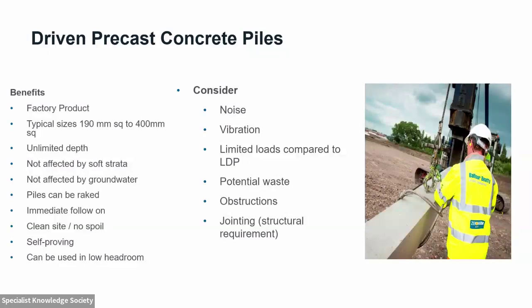set. We call it a certain number of blows, which is a certain amount of settlement in each of the piles. So you're really proving that pile's capacity every time you drive it into the ground, and that's quite a fundamental part of reducing geotechnical risk. If you can put a precast pile in the ground and prove it's actually got that load.